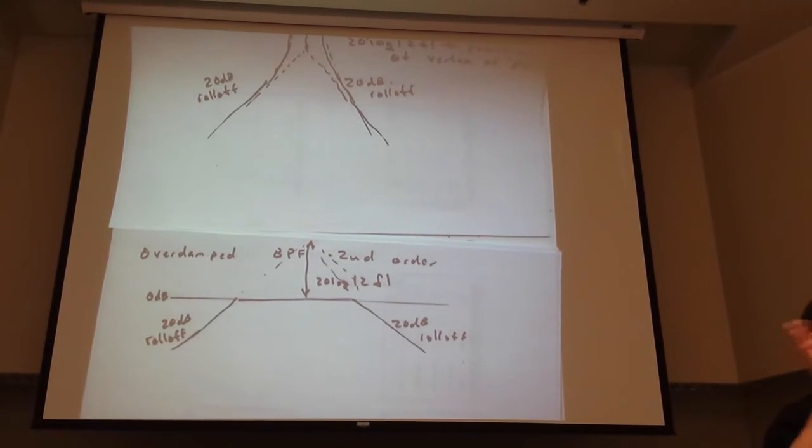At 0 dB, without any gain. If there's a K, an amplifier, of course everything shifts up. But just by itself, omega naught is at 0, but because it's critically damped, that would be minus 6 dB relative to the straight line approximation. So that means our vertex is at 6 dB.